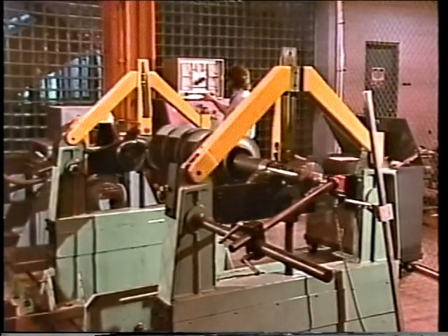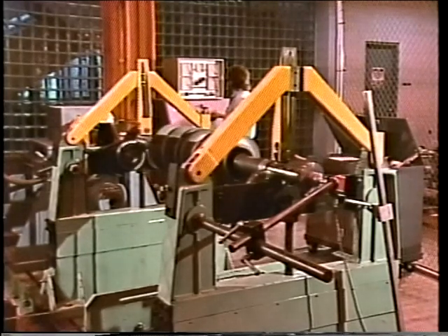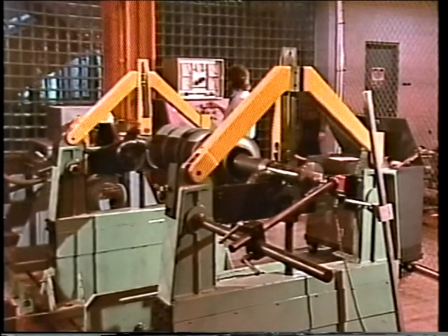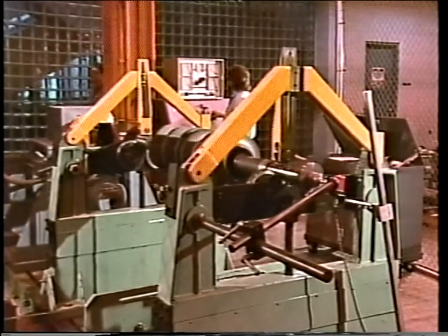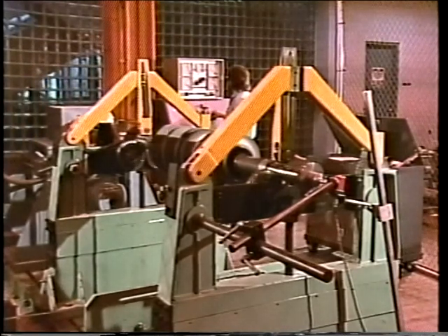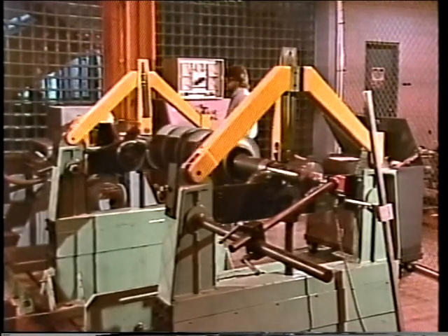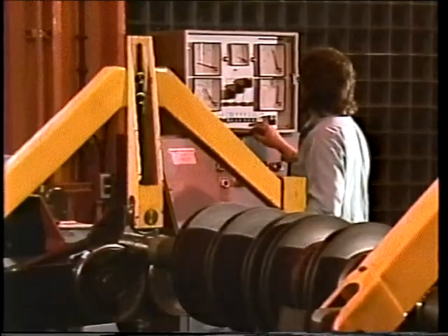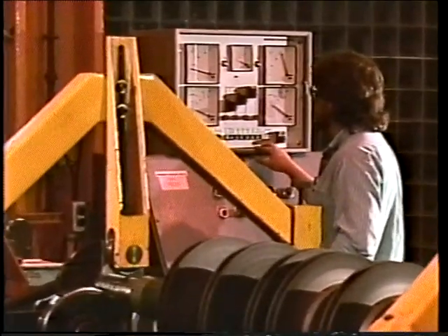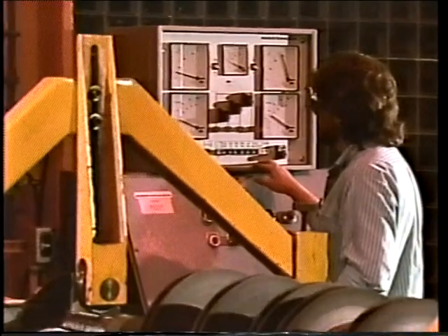One of the most common causes of vibration in rotating equipment is an imbalanced rotating element. A rotating element becomes imbalanced when its weight is not properly centered around the axis on which it rotates. The imbalance could be caused by a manufacturing error, wear, or physical damage. For example, a rotating shaft may become out of balance because of abnormal wear.